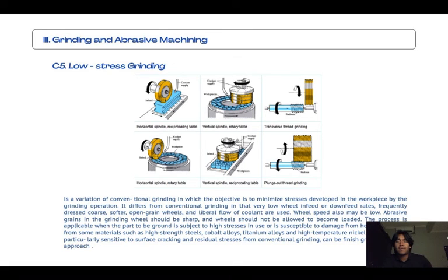So the process can provide faster metal removal than grinding with a wheel and is then often referred to as abrasive belt machining. Metal removal rates of 193 cm³ per cm of belt width are feasible with standard belts.